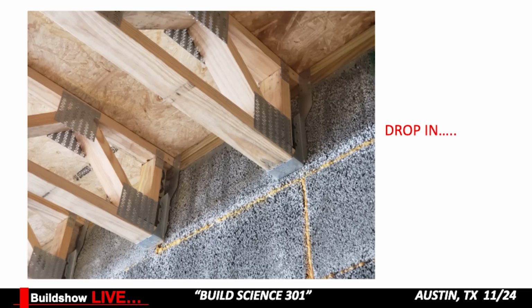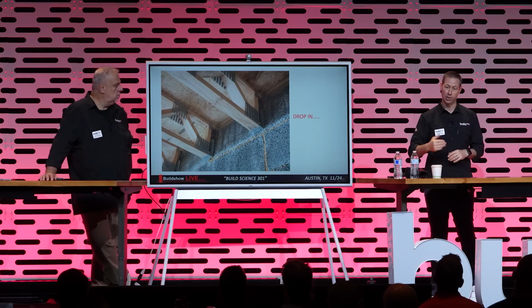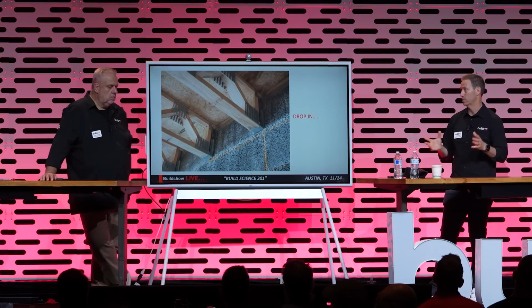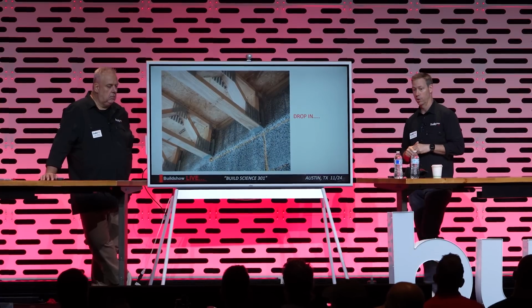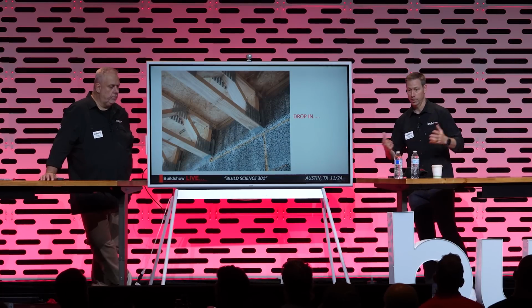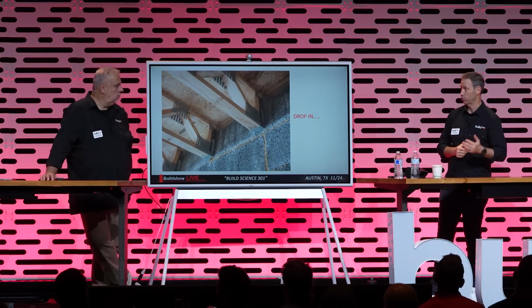So it's one step. That top hang makes a lot of sense as I look at that, because by dropping that truss down with a top hang, and I don't know what those Simpson top hangers cost, but they're not as much as doing closed cell in that band joist area, I can tell you that for sure. And now it's also perfectly air sealed there. And again, there's really no additional insulation needed.